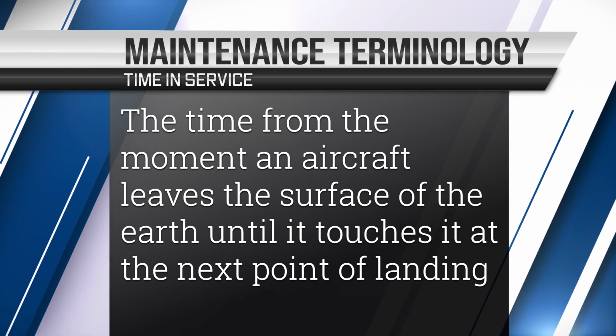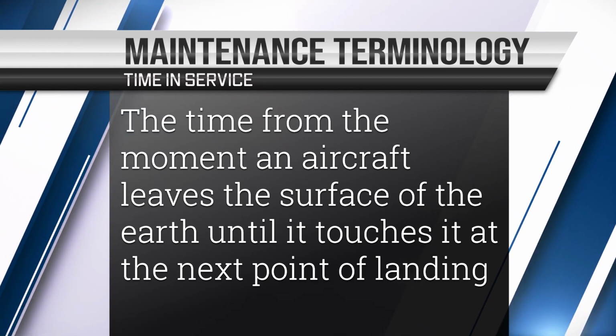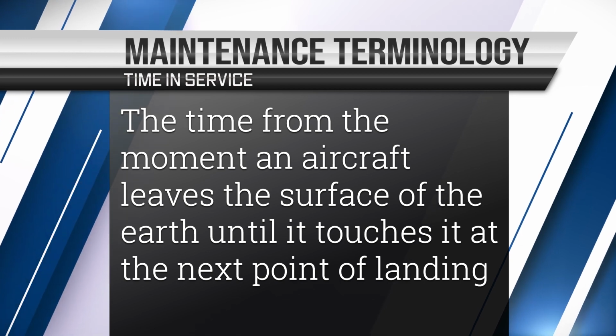Okay, time in service. All right. So time in service, with respect to maintenance time records, means the time from the moment an aircraft leaves the surface of the Earth until it touches it at the next point of landing. So time in service is an interesting one because it all comes down to the time the aircraft is actually in the air, not necessarily running.